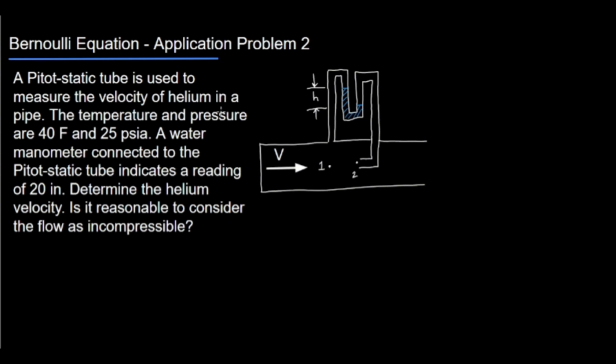So, first thing to unpack is the height we're talking about, this guy up here, is 20 inches. So this is 20 inches. And then as we're reading this manometer, keep in mind this is gaseous, this is helium, and the density of water is so much greater than helium.